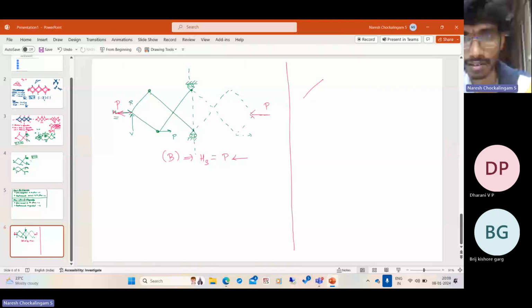Here the normal displacements and the tangential forces are 0. So you put a roller like this. Now another thing to note is here we are having a pin connected joint, so I'm putting this hinged roller.